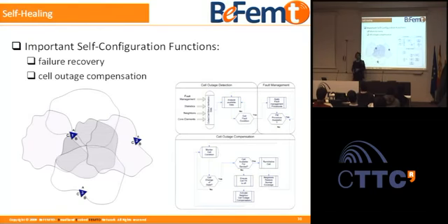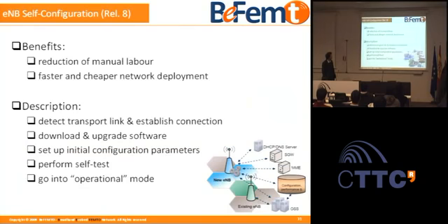So there are different things you can optimize, and I'm sure a little bit later we're going to hear about some of the opportunities we have. In general, a rule of thumb is not to change the tilt as long as you can avoid it. Touching tilts is considered a little bit dangerous in cellular network design. So you have all the procedures in place which allow you to detect whether something is in outage or not. So let's go to some functional details.